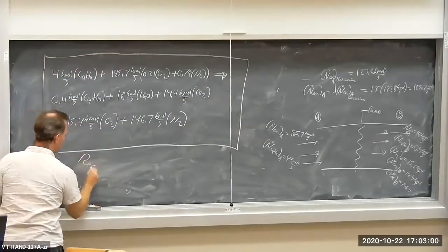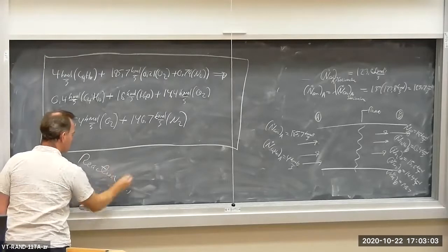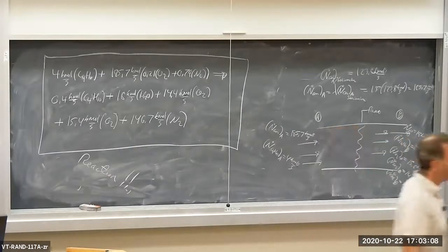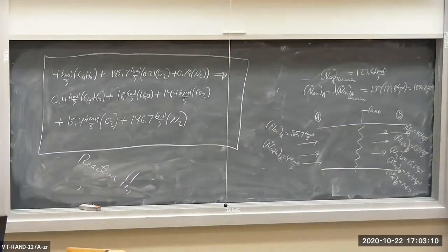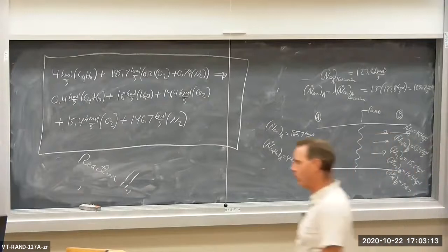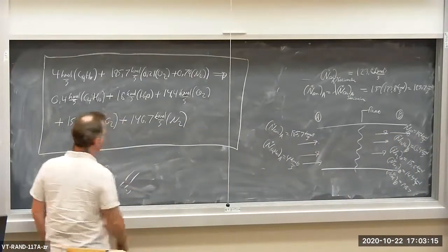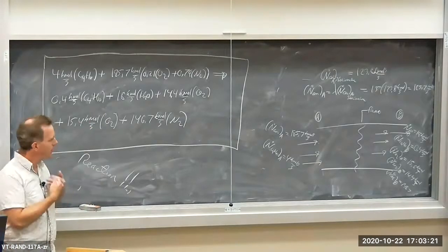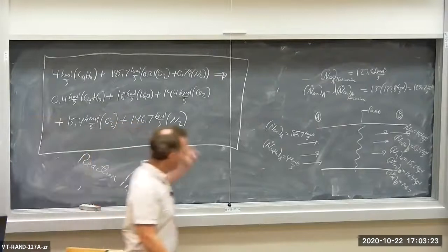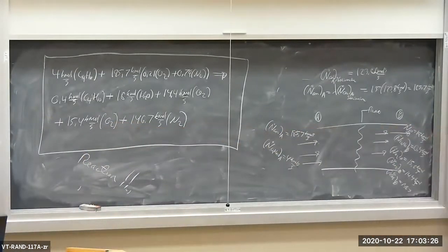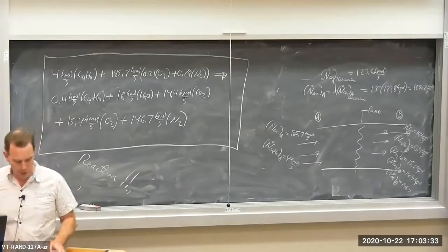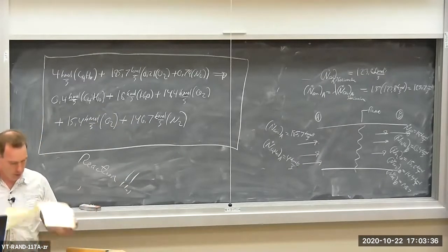It's not the reaction mechanism. Remember, the reaction mechanism, for this case, only had CO2 and H2O in the products, only had fuel and O2 in the reactants. Everything else canceled out, for stoichiometric. This includes the effects of the excess air and the incomplete combustion. This is the actual reaction. All right, ladies and gentlemen, I think that's enough material for 2 lectures here.